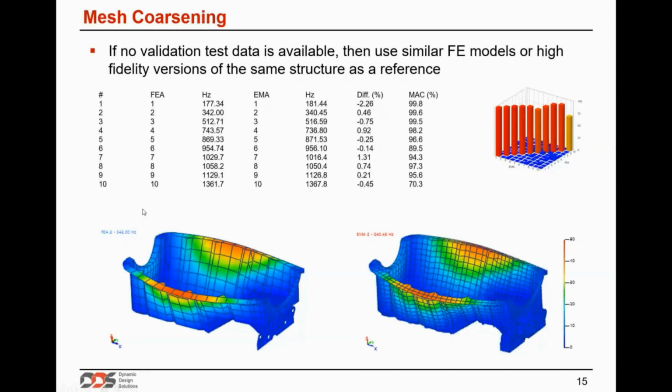Then here a simplified model is created, which is much simpler, uses only plates, no stiffener ribs, but it can produce the same frequencies and mode shapes. For acoustic simulation, the two models are equivalent. So this coarse model is to be preferred because it's much faster to do massive reanalysis compared to the refined model. So this is very common practice in the mechanical industry, but also in